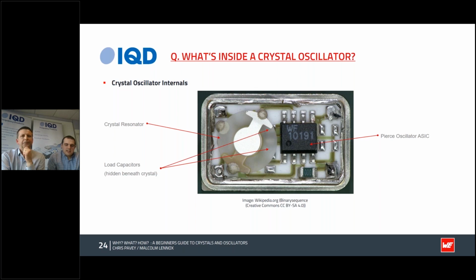For example, a temperature compensated crystal oscillator, or TCXO, where the crystal's typical response curve over temperature is compensated for, or a VCXO, or voltage controlled crystal oscillator, that has a voltage control input pin, allowing for fine adjustments of the output frequency using an analog voltage. The oscillator output can also come in many recognized standards, for example, CMOS, sine, LVDS, LVPECL, and HCSL. Additionally, the oscillator IC may have a chip enable or tri-state function input for low power applications.